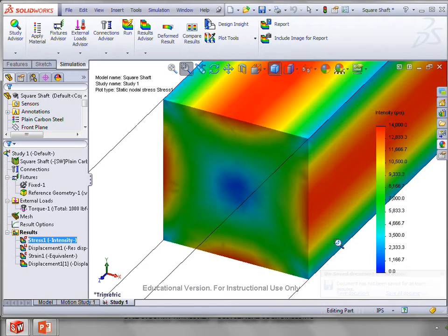That's the main difference between this and a circular shaft: if we inscribe a circle within that square, we'd probably be relatively close as far as the shear stresses go, because the material out in the corners really doesn't add much to the ability to resist the stresses.